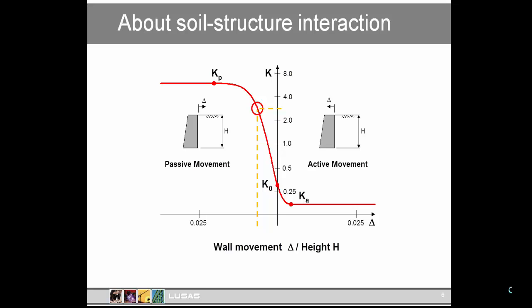In fact, in bridges with deck joints and bearings, the abutments are typically subjected to only pressures between at-rest and active, so they're low pressures. In integral abutments, when summer comes, the deck expands and the earth pressures will be significantly greater.